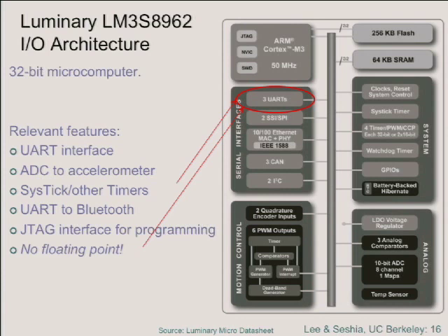So an interrupt will occur, which means that one of the threads that is currently executing stops executing. It doesn't look like it stops executing because our conceptual model is that it keeps executing, but it actually does stop executing. So suppose that we have only a single core connected on this end, and we've got a serial port link in USB 3. It's about a gigabit per second, coming through. So that means a byte every 8 nanoseconds.